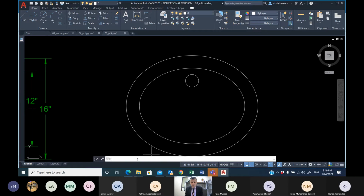You just go in here again and type RE, regenerate. If you try to zoom in or zoom out and it stopped, you can always go again with RE, regen, and enter. Now in the new CADs, this problem is being minimized, but in case it happened to you, this is what you do.